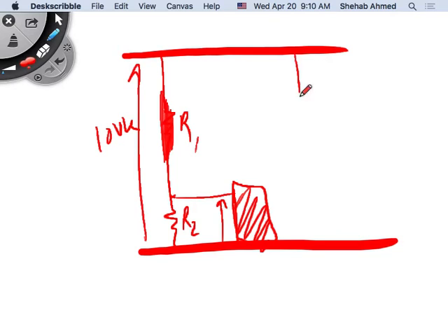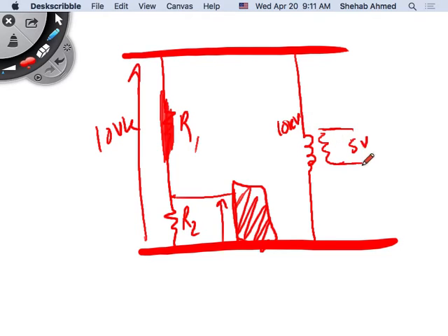That's why transformers are great, because I can put a transformer like this, and I can have here up to 5 volts from 10 kV. If you do that and you touch here, no problem. If there's a fault on the primary side, this winding touches this winding or whatever, then I don't care. I will maximum see 5 volts here. As long as I can maximum see 10 kilovolts on this winding, I will maximum see 5 volts on this side. So that's why we have transformers.